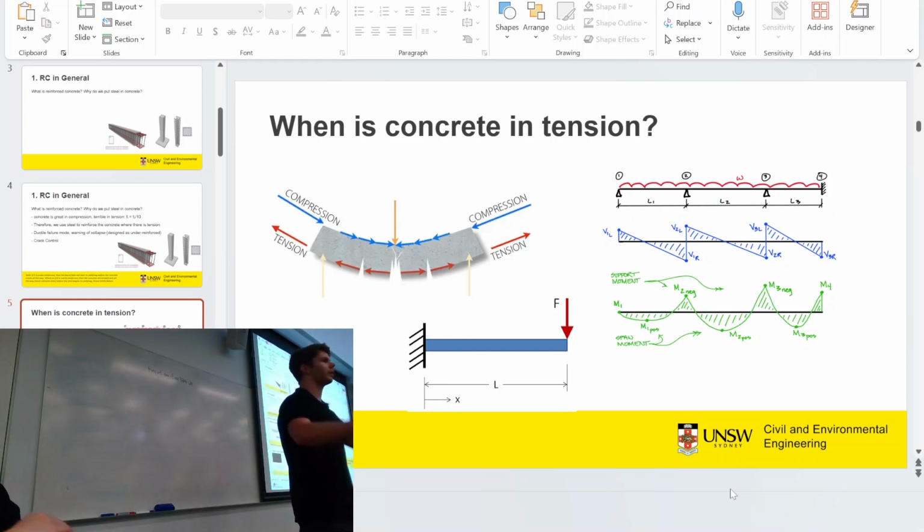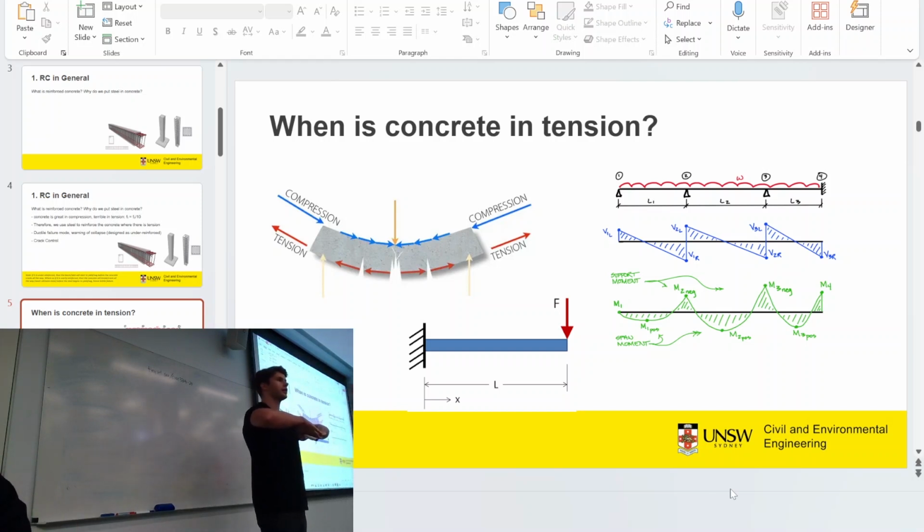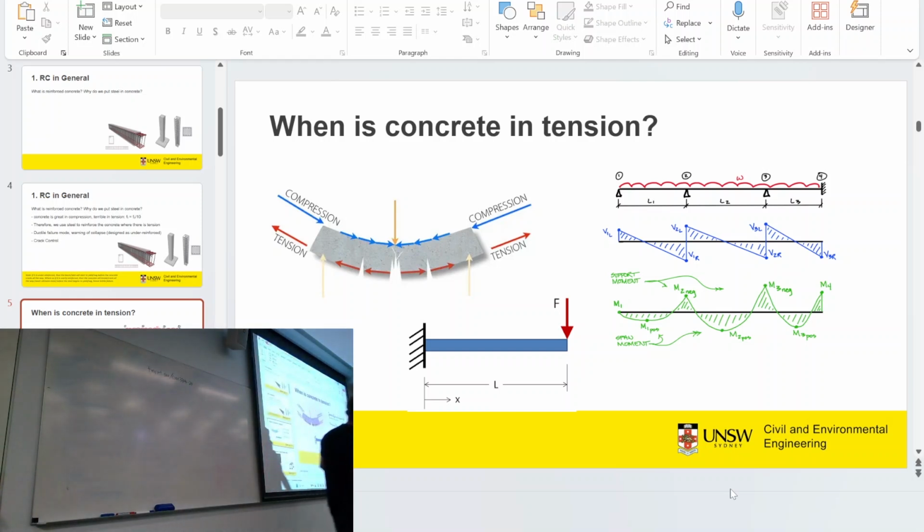That's all right. So when we've got bending, say I've got a beam that bends downwards like this. Which side is in tension? The bottom, right? Awesome. And when it's bending like this, it's hogging. So this is sagging. We call these sagging moments because that's where the beam obviously sags. And over here where you've got negative bending. So this is positive bending, negative bending.